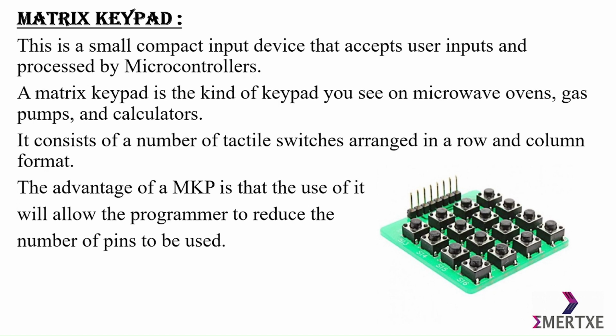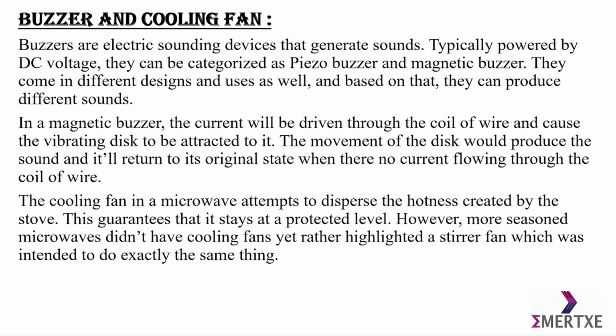And while coming to the buzzer and cooling fan, buzzers are electric sounding devices that generate sounds, typically powered by DC voltage. They can be categorized as piezo buzzers and magnetic buzzers. They come in different designs and uses as well, and based on that they can produce different sounds. In a magnetic buzzer, the current is driven through a coil of wire and causes a vibrating disc attached to it to move. The movement of the disc produces the sound, and it returns to its original state when there is no current flowing through the coil of wire.